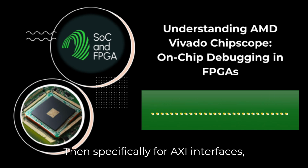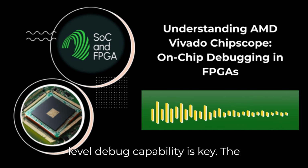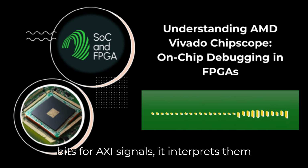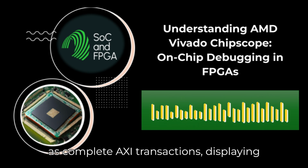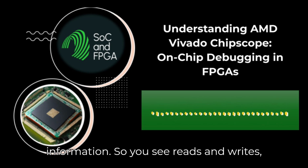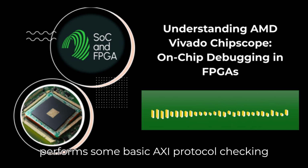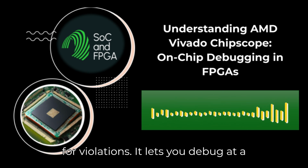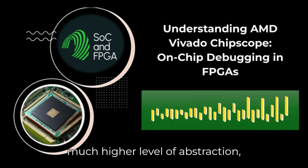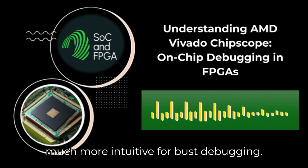Definitely. Then specifically for AXI interfaces, remember the system ILA. Its protocol-level debug capability is key. The waveform viewer doesn't just show raw bits for AXI signals. It interprets them as complete AXI transactions, displaying them as composite objects showing address, data, response codes, timing information. So you see reads and writes, not just signals wiggling. Right. It even performs some basic AXI protocol checking for violations. It lets you debug at a much higher level of abstraction, focusing on the transaction flow. That's much more intuitive for bus debugging.